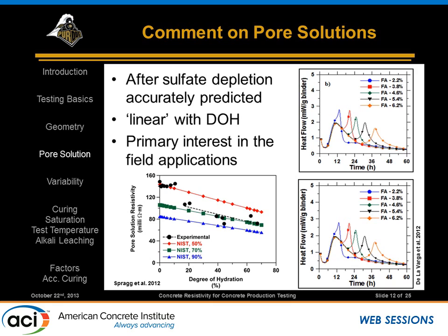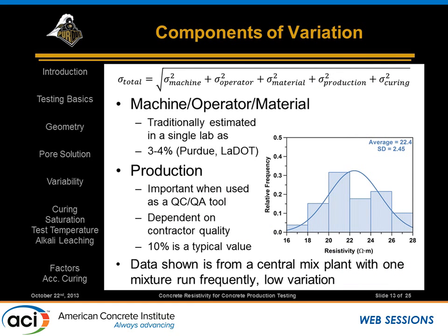But what's also important is that this pore solution conductivity is relatively linearly proportional to the degree of hydration. And if you stop and think about it, the reason it's proportional to the degree of hydration is because the volume of the porosity is proportional to the degree of hydration. The pore solution is becoming more concentrated. So at a first order, it's relatively linearly proportional after about the first 24 hours, when you get past that sulfate depletion peak.